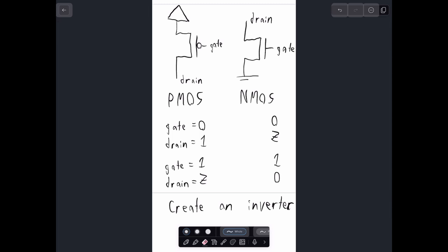Okay, I want you all to take a minute and try to remember how to do this, or figure out how to do it for the first time. So please create a NAND gate using multiple NMOS and PMOS. Remember, the PMOS can drive your 1s, so here are all your 1s, but your NMOS can only drive your 0. So here's the 0 output. Okay, begin. Start thinking about this. See if you can remember.